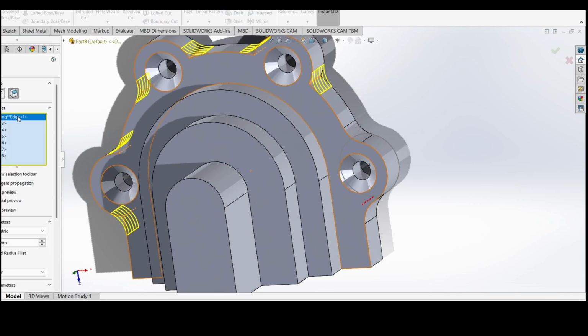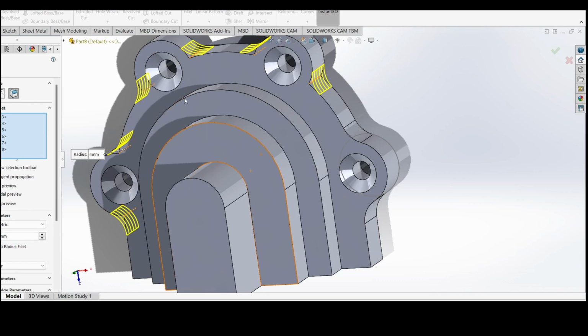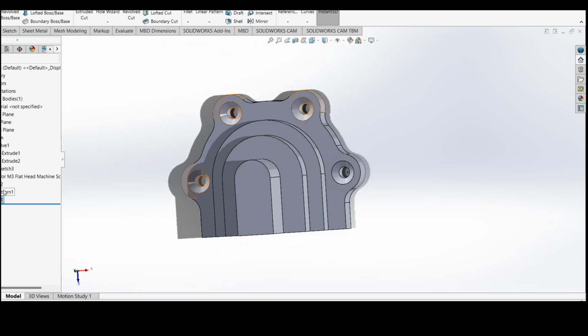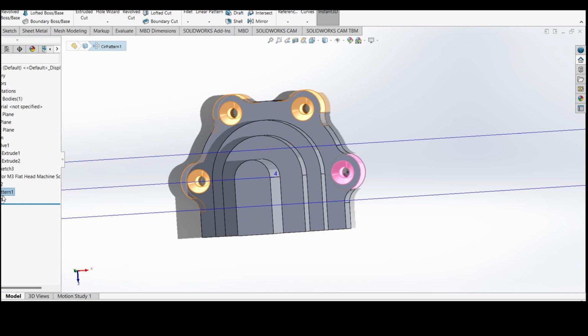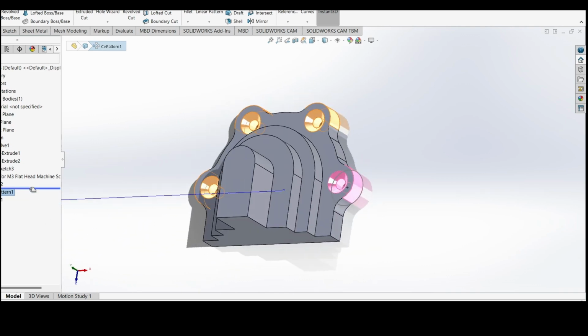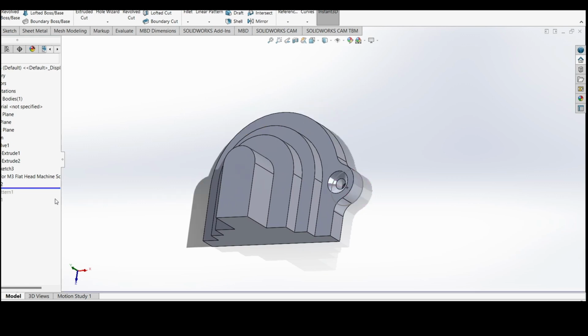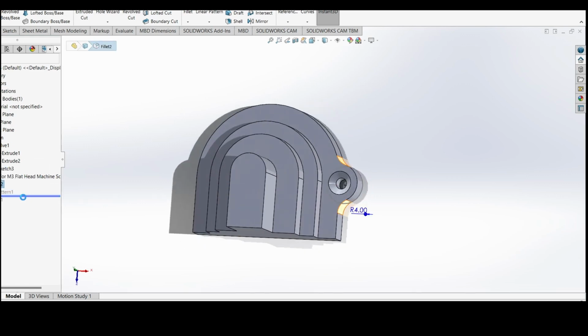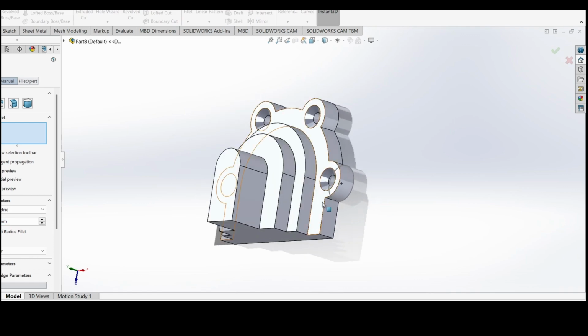There, that's fixed. Also leave your circular patterns for the end, but not before your fillets. All right. So with that in mind, maybe I'll undo these for now, just in case. Sorry, I'm getting all confused which fillet was what because I was trying to do something. All right, well, I'll just do it again.